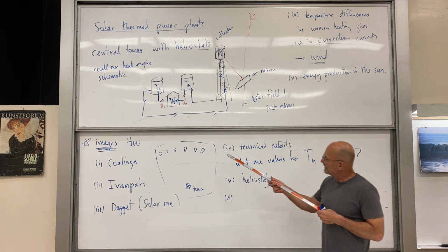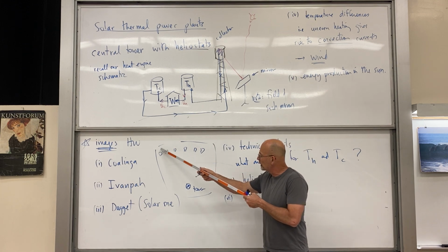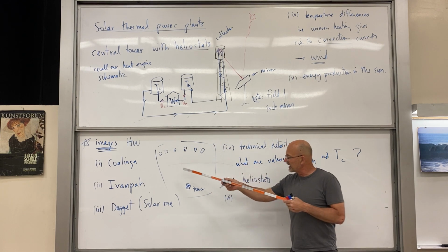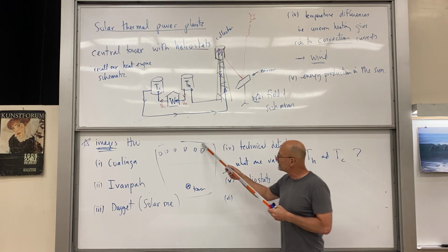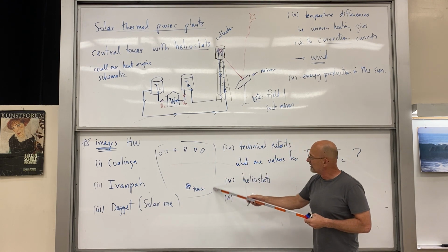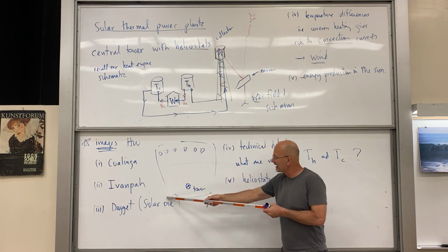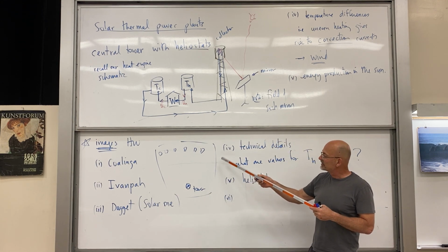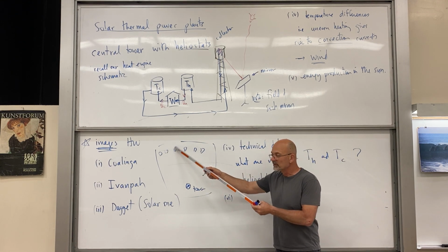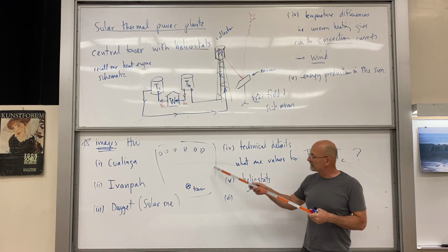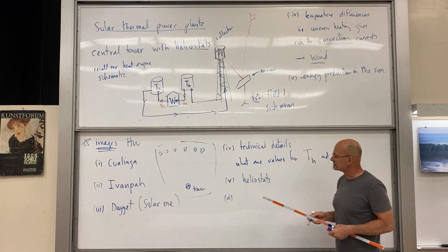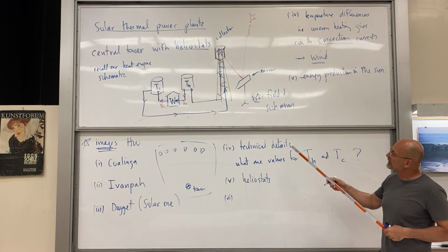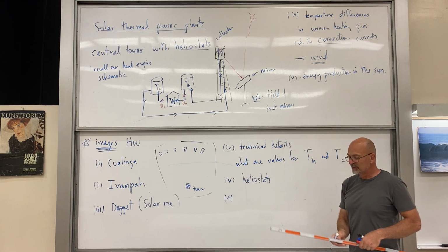For one of these, what I really prefer for you to do is zoom in on it and, from, say, the Google Maps program, estimate the area of the mirrors, and you can then get an estimate of the actual power that can be derived. So that's something you want to think about when you're generating these things.